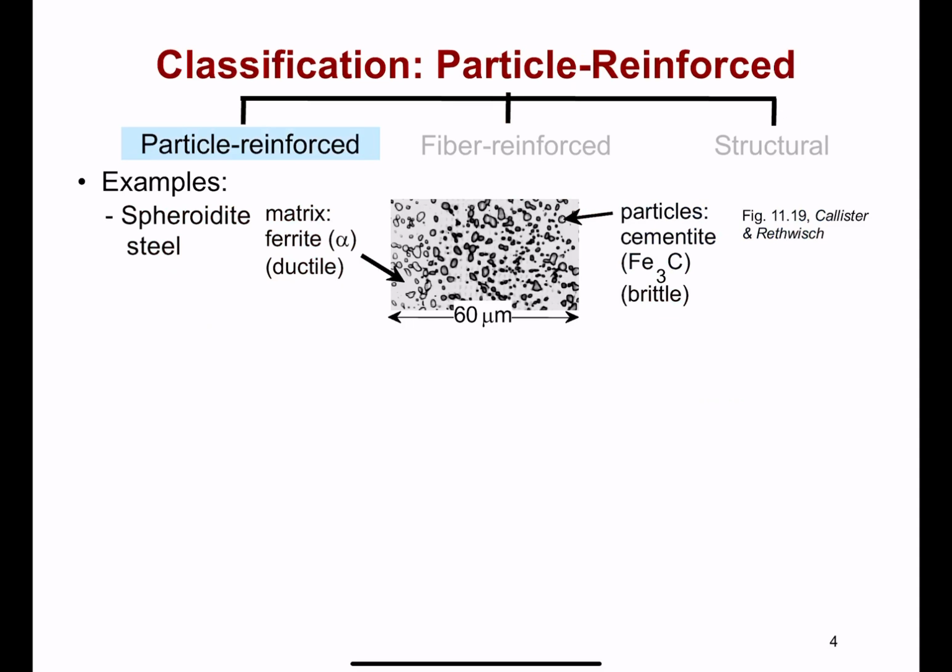Okay, looking deeper at some options for particle reinforced composites. We've seen before in the cast iron series that we could have cementite reinforcement, or particles that would phase separate in the phase diagram that we learned in our previous lessons, and that these would act to prevent shear slip planes that would otherwise lead to plastic deformation in the pure iron sample.